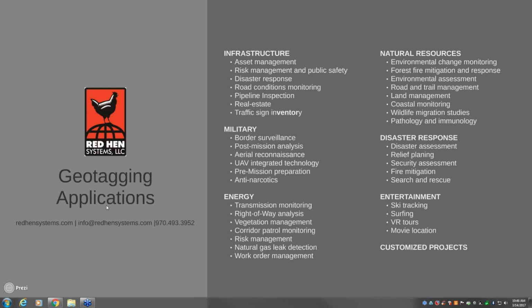Yeah, absolutely. And then one last question before we go here, and that is, is there a version of VMS GeoVideo for ArcMap 10? So I don't think we have anything like that. The full motion video which is available in ArcMap is a post-process. You need to have a CSV file with all your metadata in a particular format which ESRI asks for, and then it calculates the full field of view, and then it can be shown on a full motion video. So it's not a version which we might think about doing, I guess.